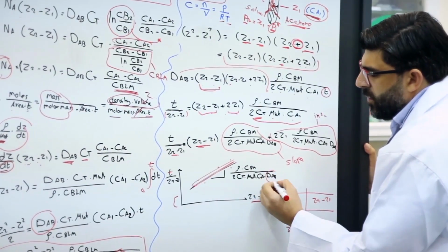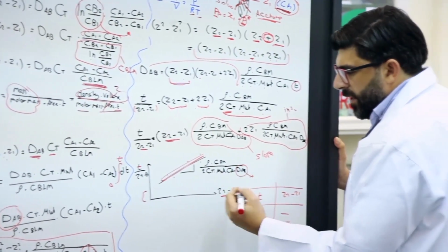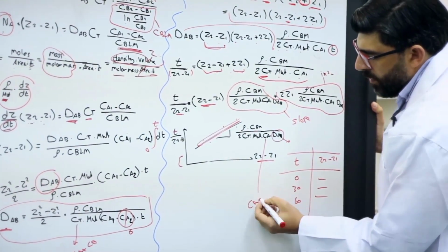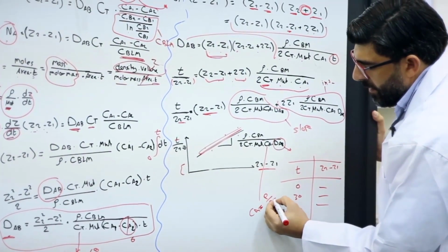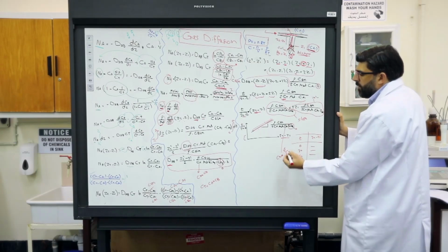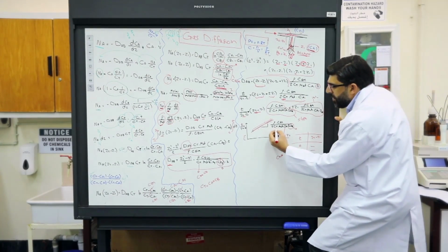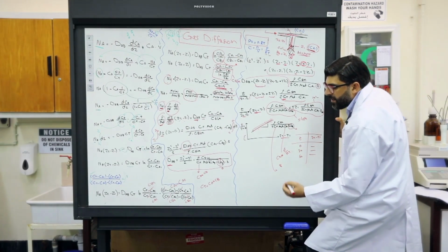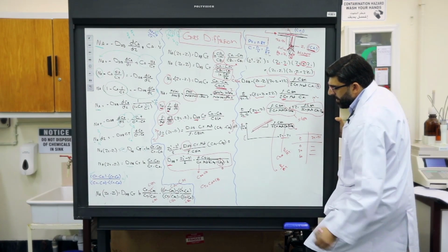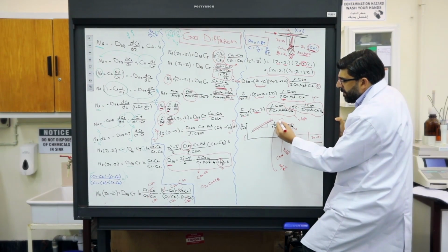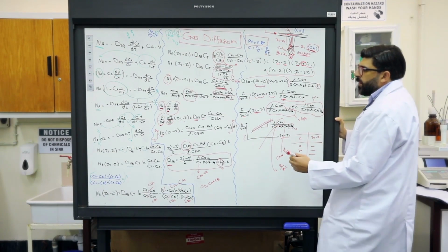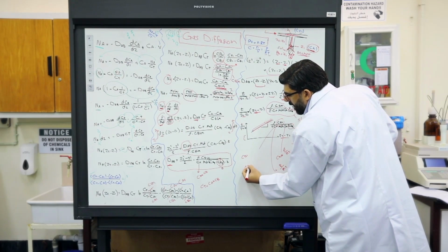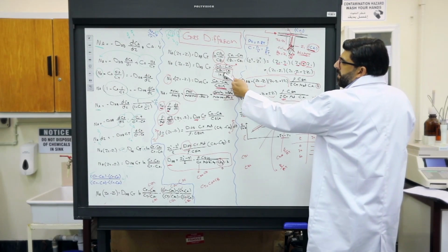It can tell you the DAB, because you already know how to calculate CA1, which is equal to P over RT, okay? P we got from the Antoine equation, and for CT it is the total pressure, atmospheric pressure, because we are working at atmospheric pressure, over RT, okay? Then again for CBM, we want CB1 and CB2 in order to find CBM.